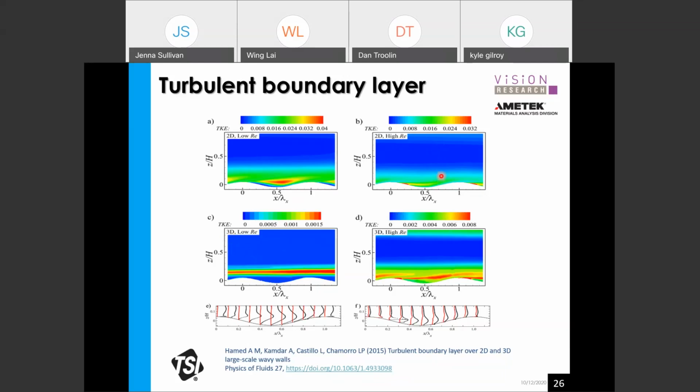Again, based on just the 2D information, the limited information of the turbulent kinetic energy that we saw, particularly on the trough area of the turbulent boundary layer. But by using the stereoscopic systems, we were able to actually see much more details, meaning that there's a strong third component going through the light sheet, generating a much higher turbulent kinetic energy that we can discover using the stereoscopic arrangement.